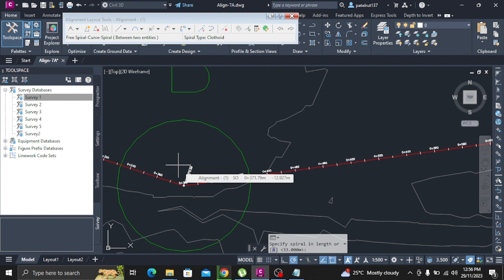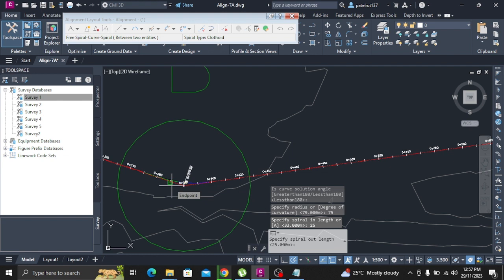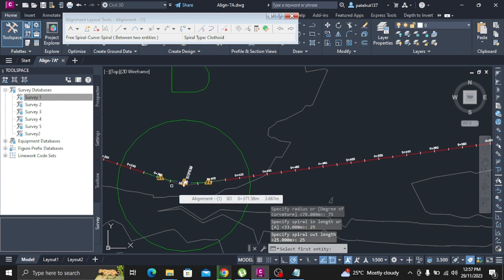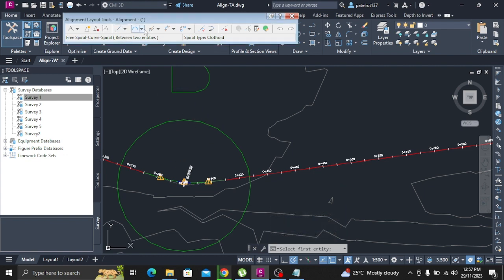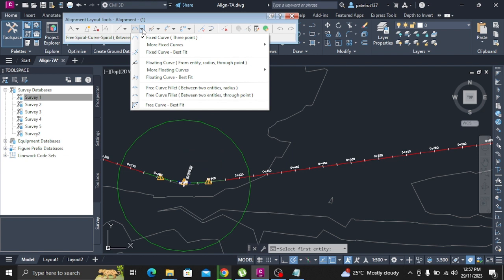Click If. The If function is displayed in the expression field. Click Insert Property. Select Design Speed. In the expression field, use the keypad to enter greater than or equal to 50, including the comma, after the design speed property. Click Insert Property. Select Length. In the expression field, enter equals 310, 1, including the closing parenthesis. The following formula should be displayed in the expression field.